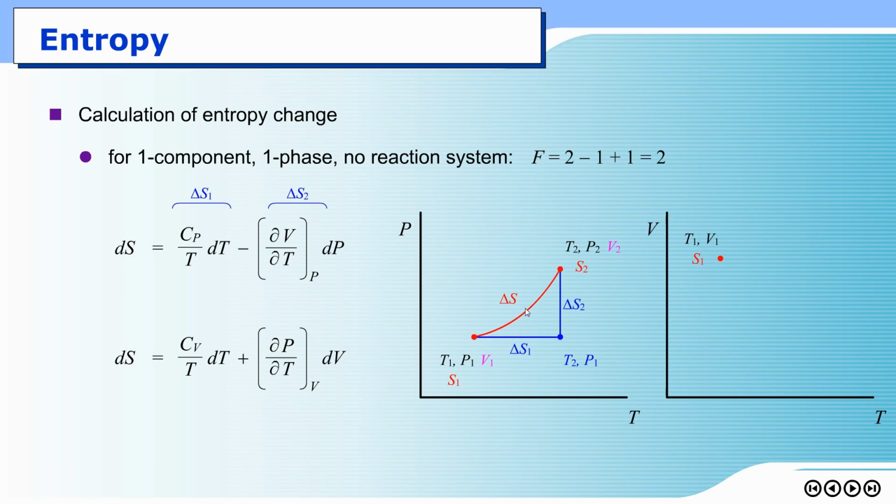When you increase the pressure, your system would be compressed and the molar volume is supposed to be lower. So if you plot within the P volume temperature plot, the initial point would be up here and the final state would be down here, and the process path would be drawn like this. Okay, so once again the delta S in this plot and delta S in that plot are essentially the same. But the way to visualize it, if you use this equation, the first term is integrated with respect to temperature, so it means that you change from the initial state by changing temperature under the condition of constant volume. Okay, so it's going under the condition of constant volume from here to there. If delta S here is called delta S3, this particular term is essentially delta S3.